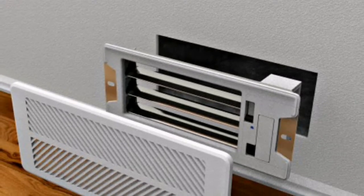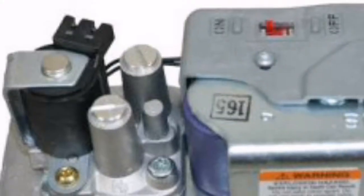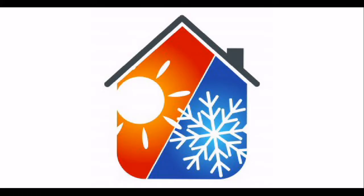The zone control panel then activates the heating and cooling functions as required to meet the individual needs of each room. A multi-stage furnace is highly recommended for this system. As with all conventional zoning systems, you cannot simultaneously heat and cool.